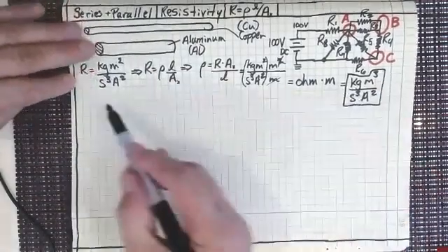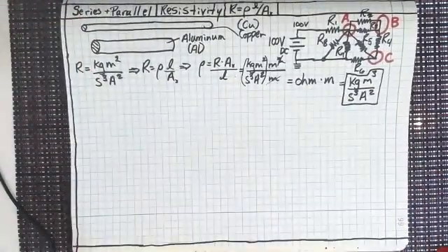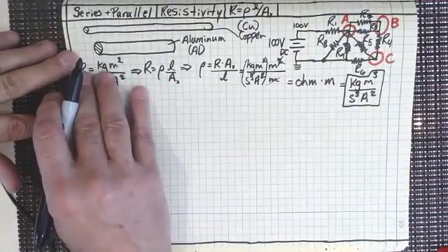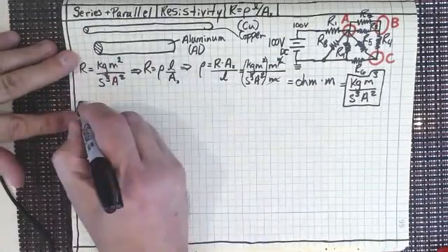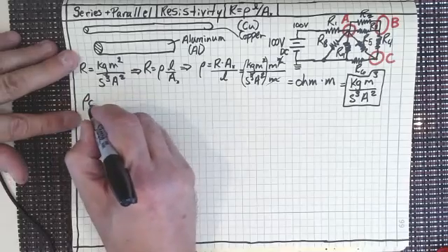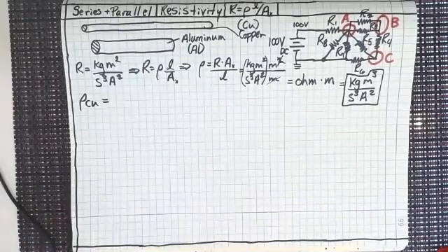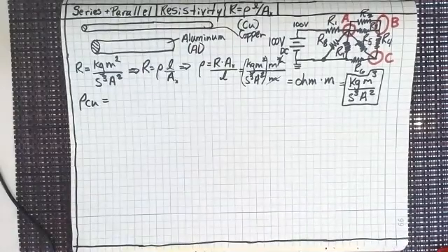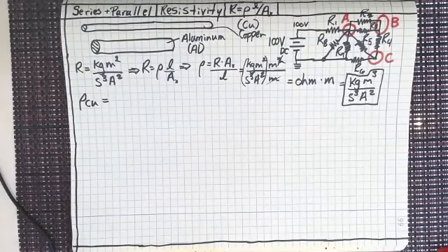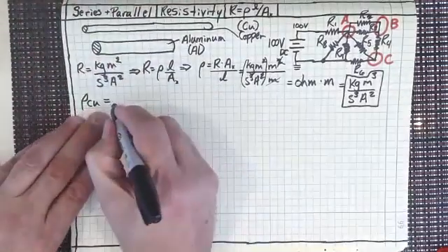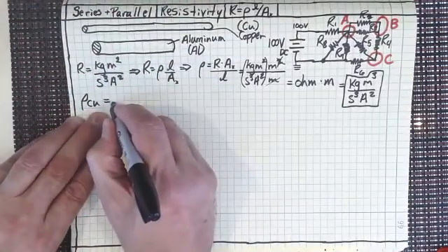So that's the resistivity, and I want to look at resistance for two different types of things. The resistivity for copper, and I'm going to use the one in your book, although I don't really use this. I use 16 times 10 to the minus 9 ohm meters, or 16 ohm nanometers, is the way that I usually look at it. But let's just do that.